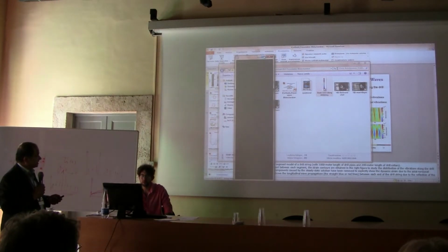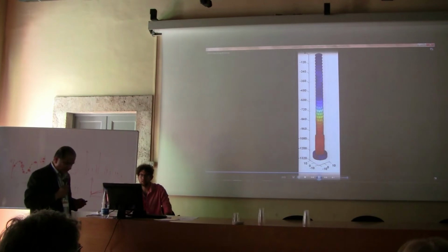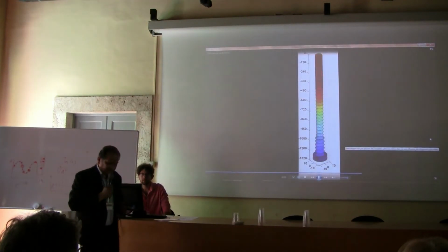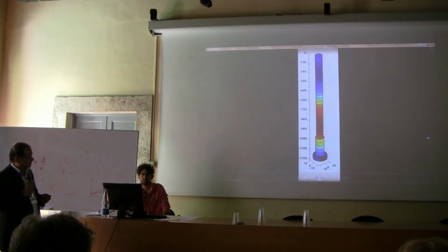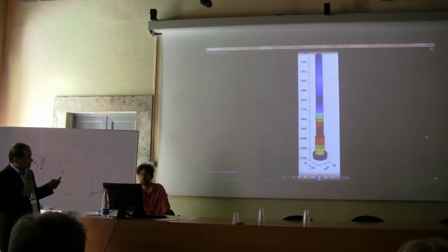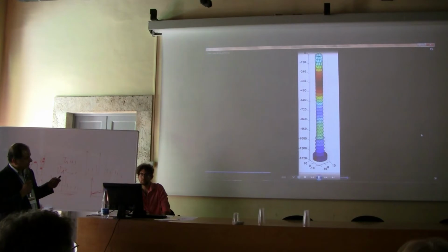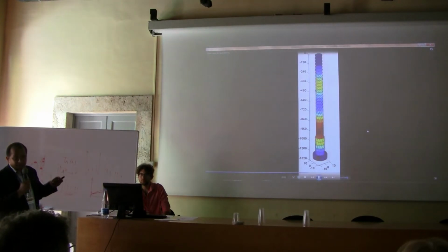So what you'll see in the illustration is if I were to go through an actual drilling operation, based on the system that you see, the waves traveling up the drill string. This is basically the distribution of the von Mises stress as the wave runs up from the bottom, where the cutting action takes place, all the way up to the top.